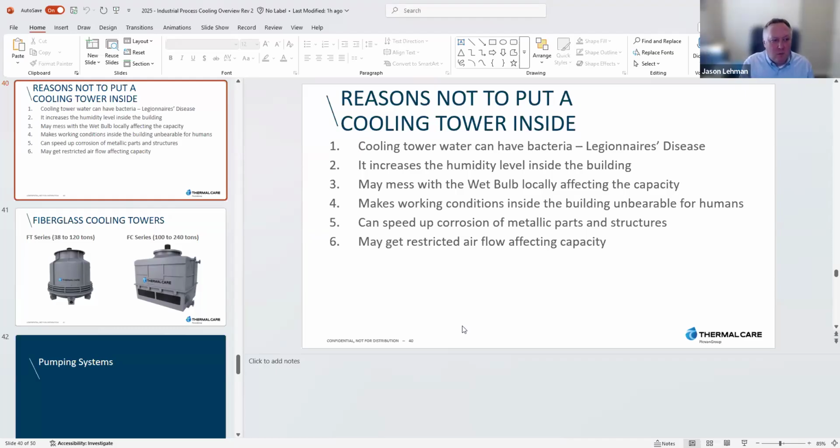Generally speaking, you can. That's kind of a loaded question because it depends on how steady your steady state is. A lot of times we're plus or minus 2 degrees, plus or minus a degree. Anything less than that, you're really at the mercy of the temperature probe precision and accuracy. So I would say, if we can get away with plus or minus 2, we can do that all day. Plus or minus 1 Fahrenheit is possible, but that really is more process dependent.